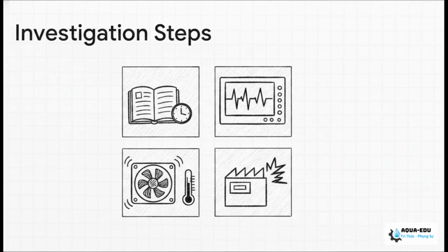First, inspect the maintenance logs and the physical age of the rectifier unit. The history usually tells the story. Second, and please listen to me on this, put an oscilloscope on the DC feed. A regular multimeter will not cut it. You need an oscilloscope to physically see that ripple wave and confirm if your filter capacitors are toast. Third, check the power supply cabinet. Are the cooling fans spinning? Are the heat sinks choked with dust? And finally, walk the perimeter. Look for new installations of VFDs or heavy machinery near your runs that might be injecting EMI noise. Physical verification solves problems. Assumptions just lead to more downtime.